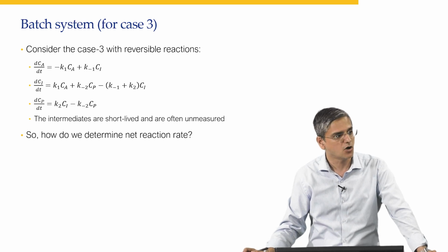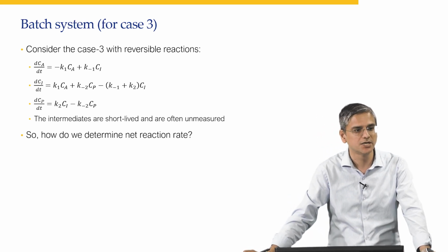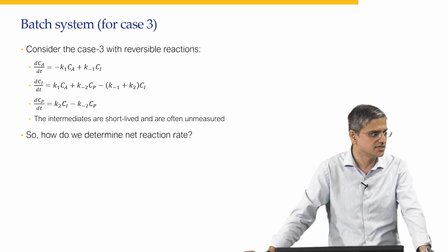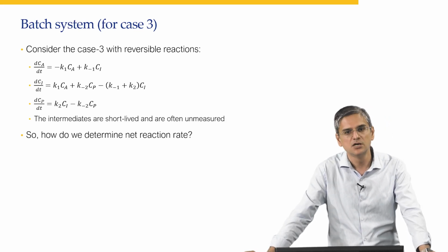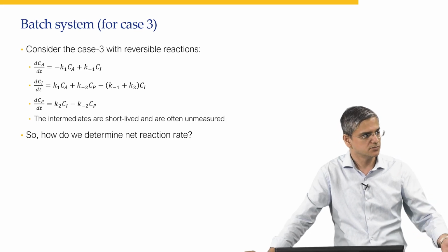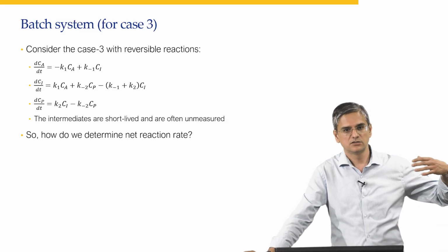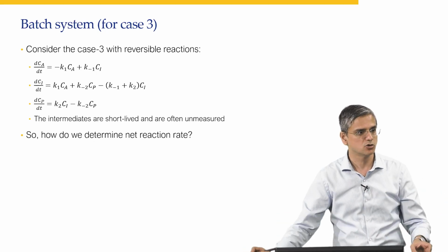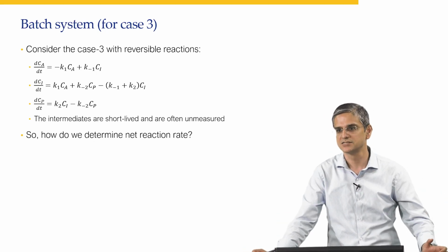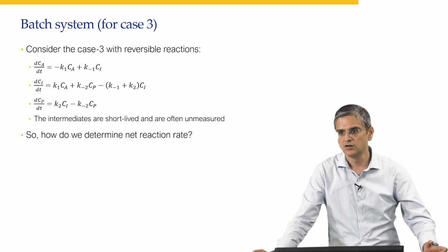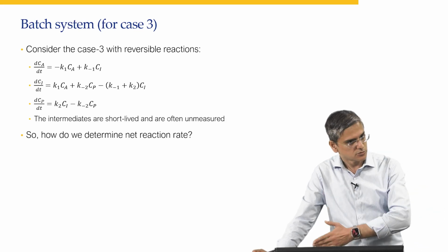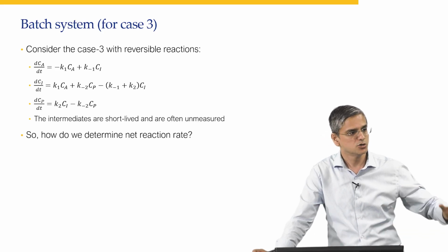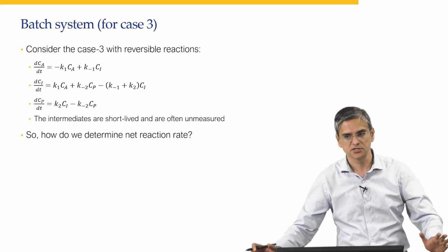Where does the term pseudo steady state come from? Okay, because all of these analyses are usually done assuming batch system. Why are these analyses done with batch system? Simply because if it is a flow system, addition and removal of species in your control volume can affect your analysis. Okay. Starting from mechanism and going on to rate expression, you only want to focus on reaction rates.